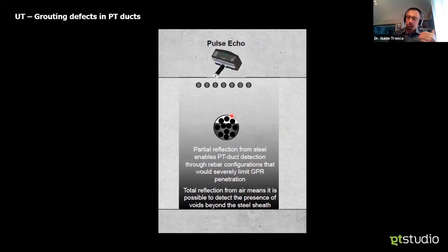Strands are well protected in a properly injected duct. But whenever, for manufacturing reasons, the quality of injection is not perfect, we open the door for water to filter in and start eroding the strands. The effect is dramatic, with the risk of an invisible and unannounced collapse.